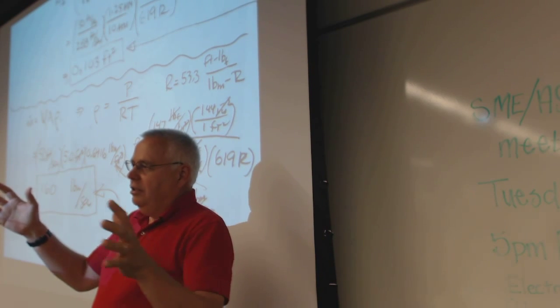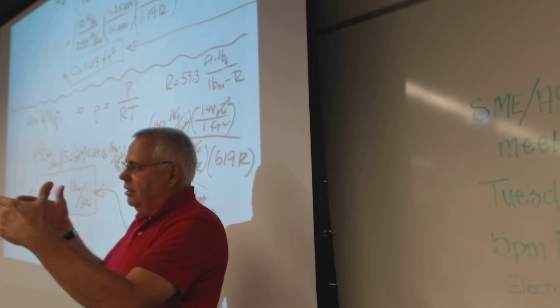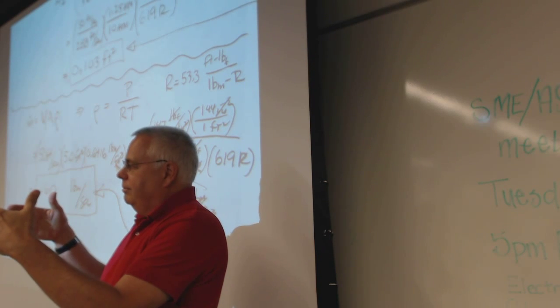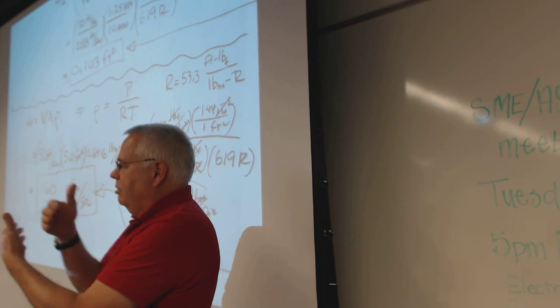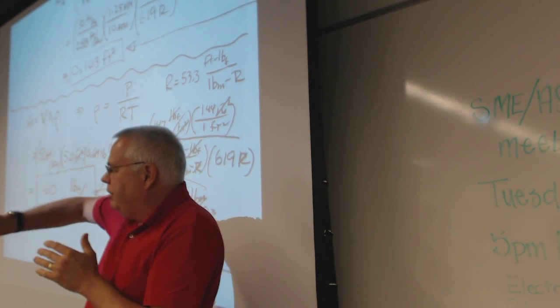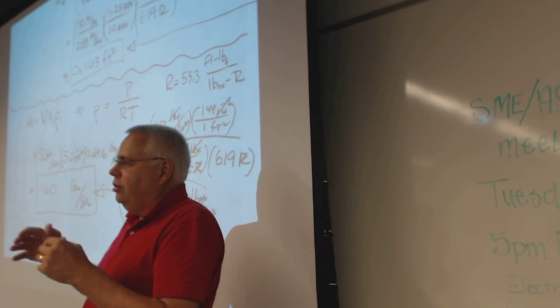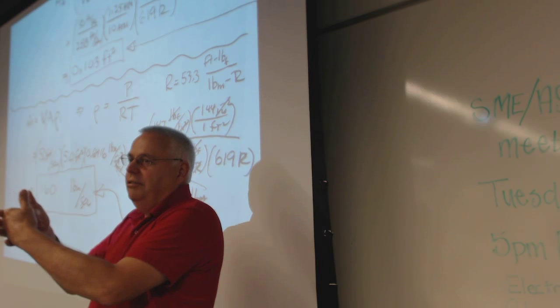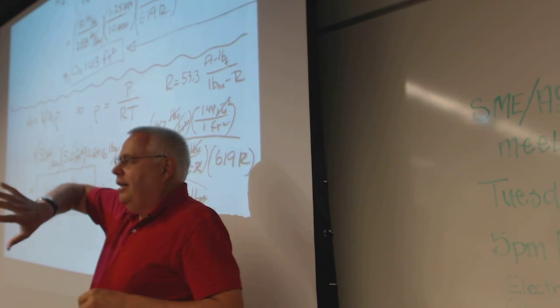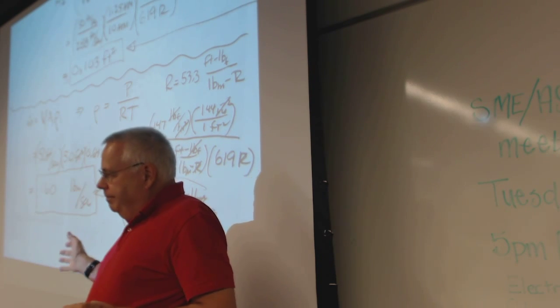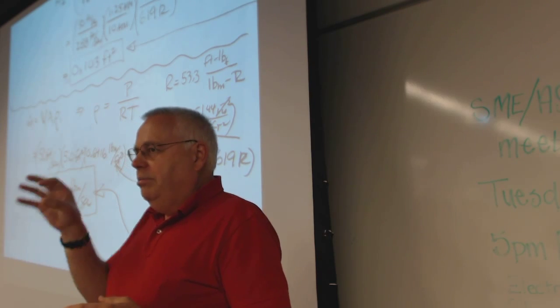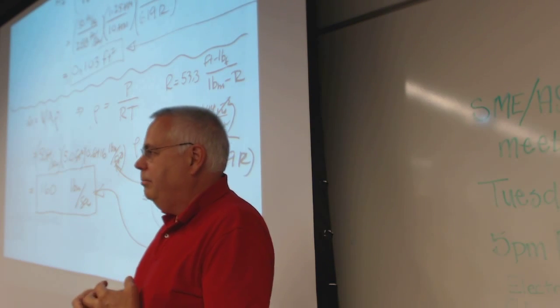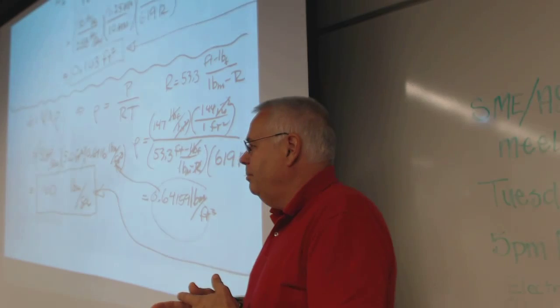They design aircraft engines for cruising for that shock wave such that the pressures come in really fast. It doesn't blow through the engine. It comes up to a place where it nozzles down to the point where it goes essentially sonic, and it creates a shock wave, and then it pressurizes the engine. It changes it from speed to pressure. The speed that the air is going generates the pressure inlet for the compressor side of the turbine.